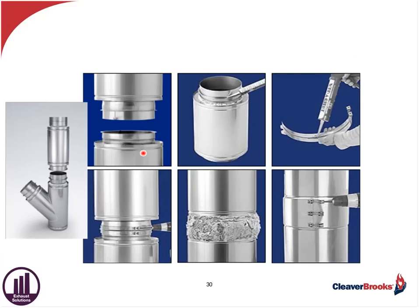So when you're choosing these materials, look at the manufacturer and how they go together. How are these stack and breeching sections designed? Are they butted flanges, or are they male-female connections, which in fact could save some labor out there in the field?